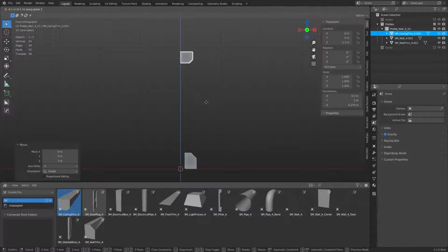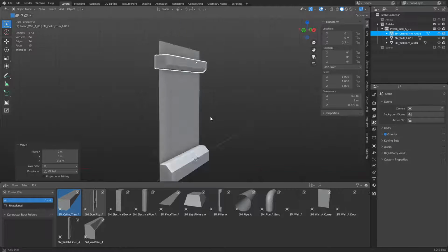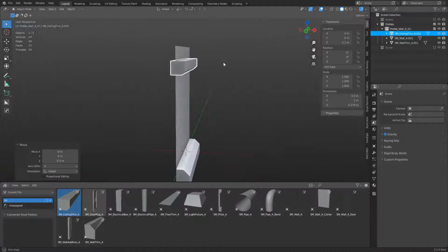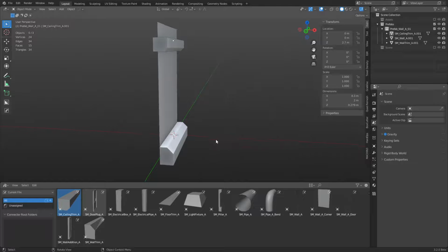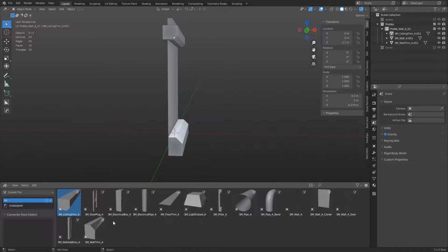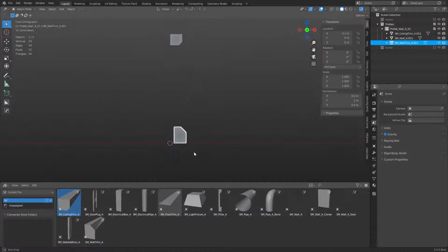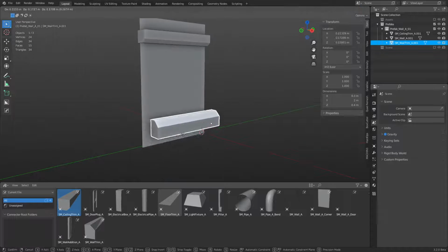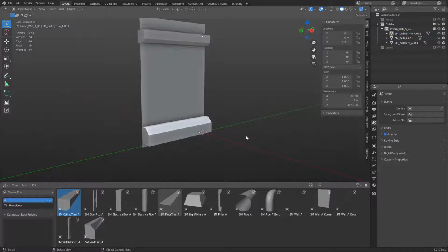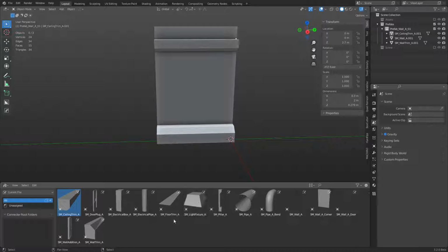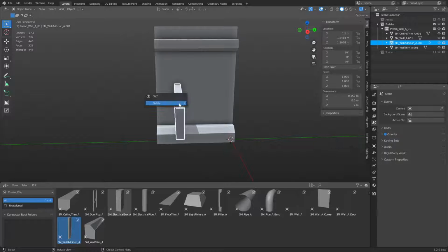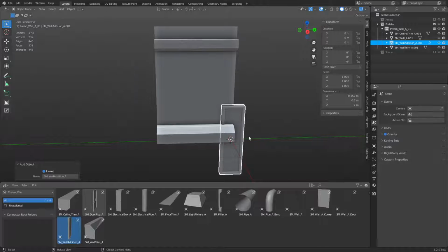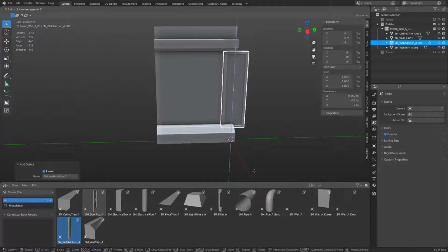And we could leave this one in if we wanted. I want a 30 centimeter drop when it comes to the ceiling here. I have a little room to play up there, but in this case, this should work out okay. Also, I'm going to be putting a 10 centimeter floor in, so I can bump that up like so. And let's go ahead and add that accent to this one real quick. Wall addition. See, you don't drag it onto the mesh, drag it here. Just bump it out like so.